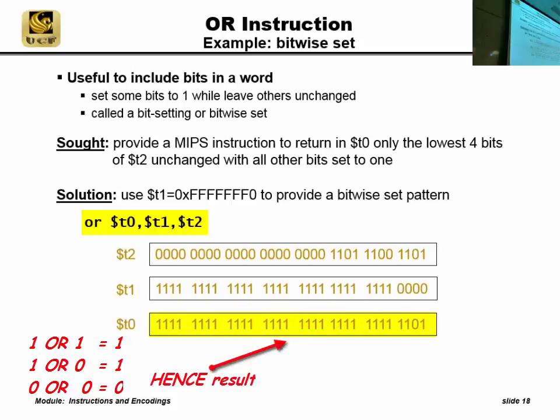This is bitwise OR, so we look inside T1 and T2. If these are the values that we have, what do you think is going to happen? Since this is the OR mask, all the bits that are 1 are going to be propagated to the answer. See the answer here? Anything that's a 1 here comes in the output, as well as anything that's a 1 in the other input. We say that OR is 1 sensitive. Just keep it in mind.